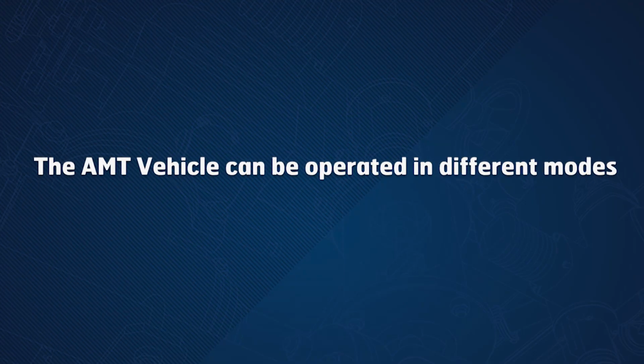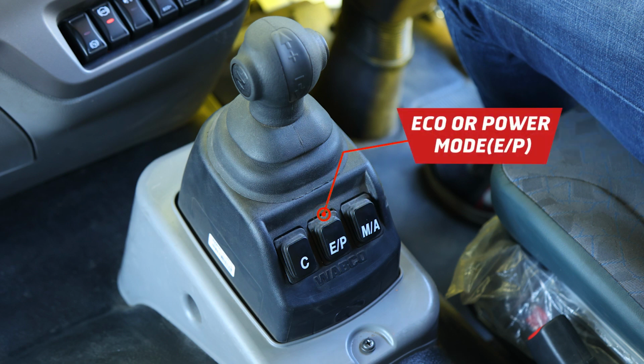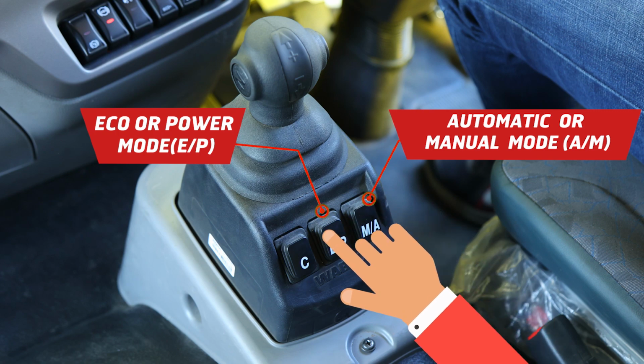The AMT vehicle can be operated in different modes: automatic or manual mode, AM; eco or power mode, EP; and crawler mode. AM and EP modes will change based on button press.